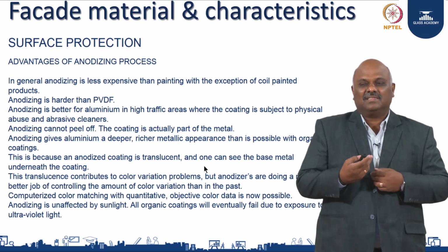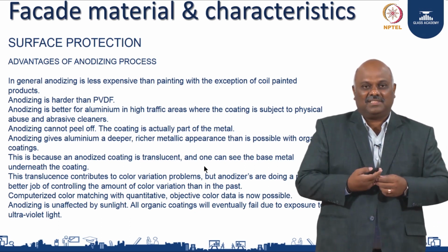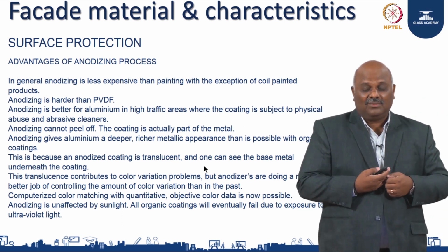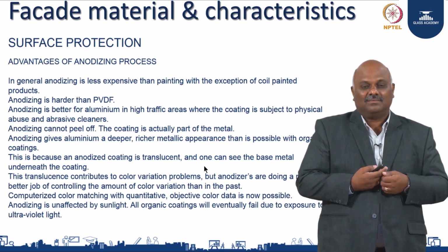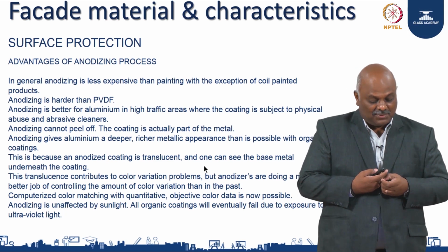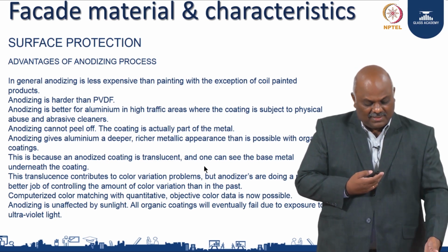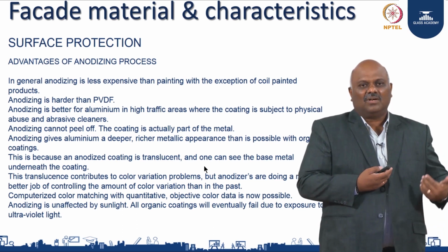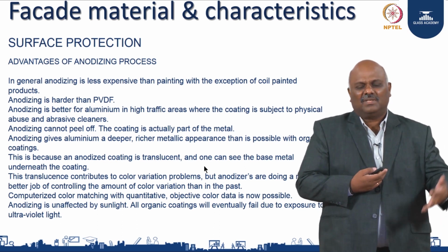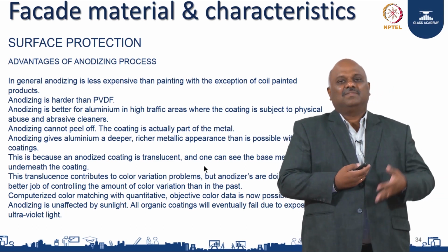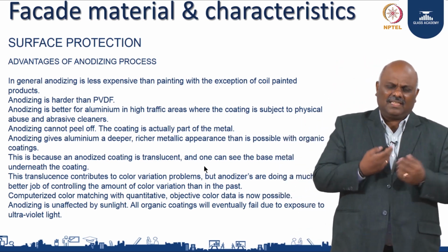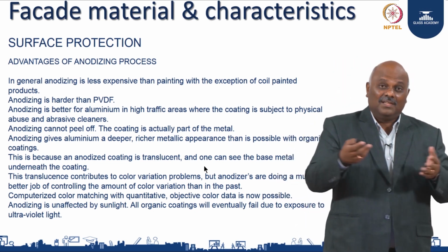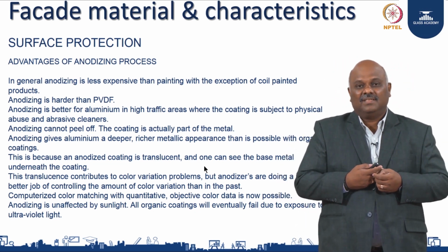Again, it is harder because it's not a coating, it's a surface change. PVDF is a form of car paint, right? You can paint it by spray painting the system as well. You can read through the different systems, which call for different colors. There are advanced systems available. PVDF is good for external conditions where you have a lot of corrosion happening, or a building facing the sea front.